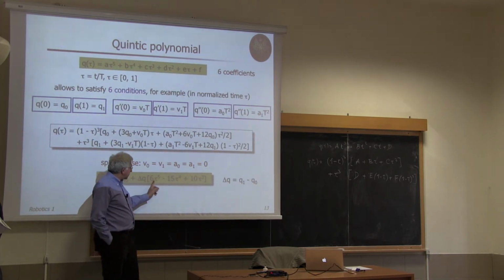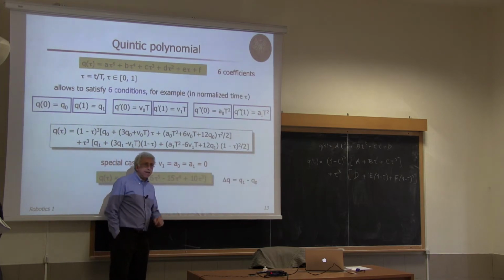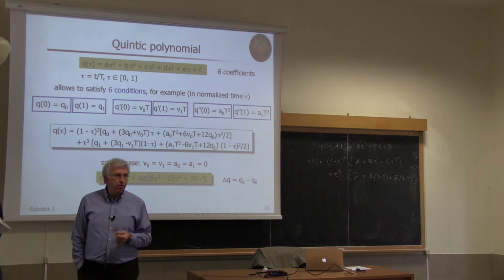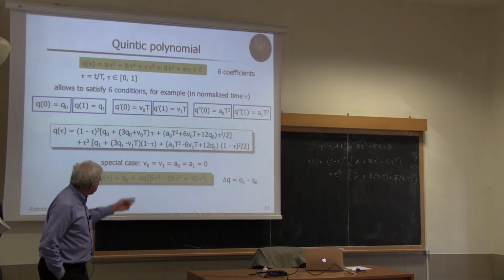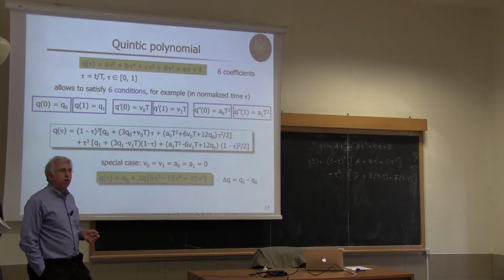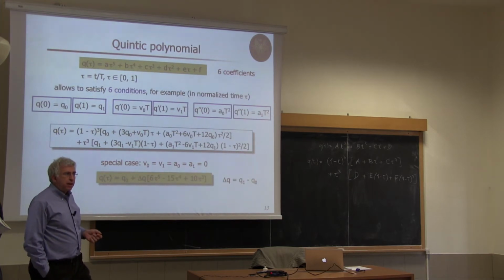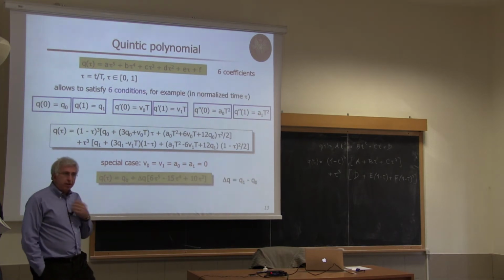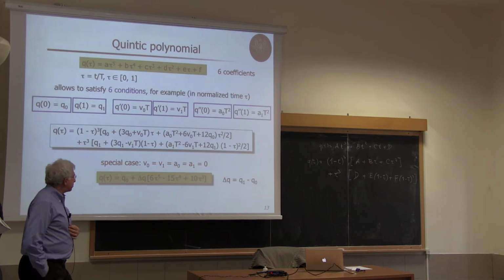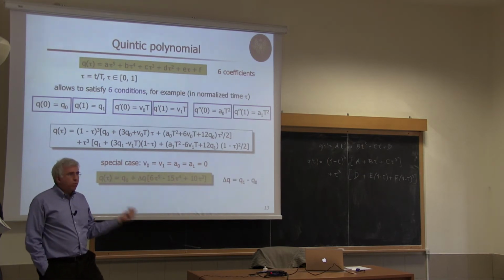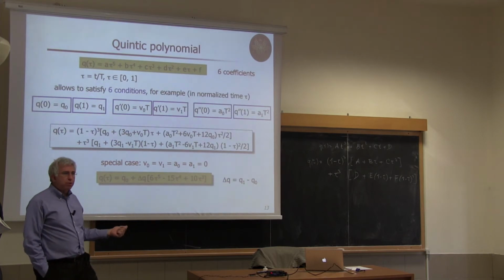And again you find 6, minus 15, 10. So only half of the coefficients are different from 0. You see there are no terms in tau squared, in tau, or the constant term. So only half of the coefficients of higher order terms are different from 0. They are integers, no matter what time you want to impose for this motion.